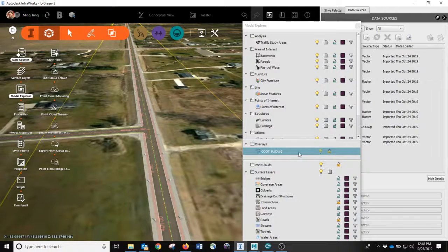Okay, so that is the layer I locked. And also I locked the intersections and the roads because these are assigned to the GAs. I don't want you to accidentally delete or relocate the roads, so I locked them. But for some reason, if you do want to select or modify, you can unlock these two layers, roads and intersection.